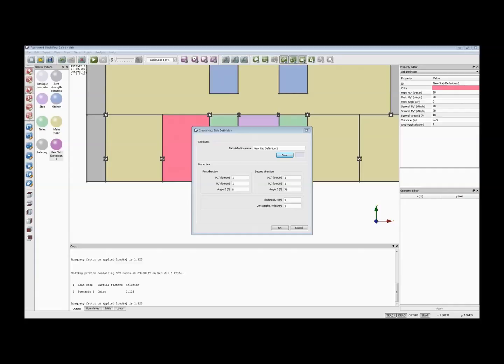And there's a similar message, probably the final one before we wrap up. Are MP values provided by manufacturers? Reinforced concrete isn't really something that manufacturers would deal with, because we've got rebar manufacturers, and we've also got concrete, which is a material separate and distinct from the reinforcement. So it's the combined action of those two things which gives us the plastic moment of resistance. So it's a standard operation to calculate the MP value.